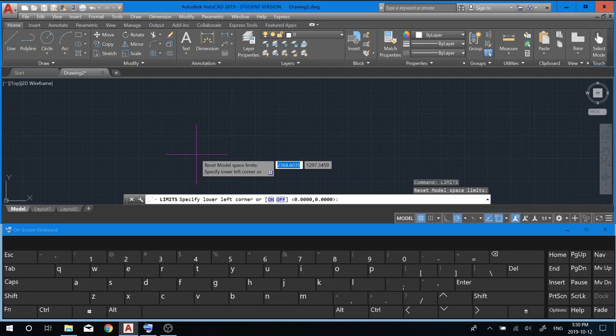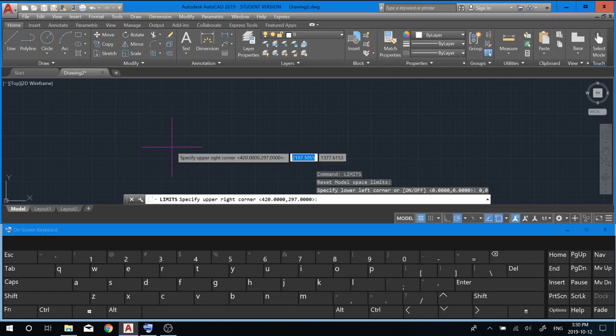So we're going to set it to 0, and then we need to shift over to the second box, which you can't do with your cursor, because if you move your cursor, it just moves the whole thing. But to jump over to this box here, you have to hit either comma or tab. Either comma or tab will swap over to the next box, and 0, and I'm going to hit, once again, spacebar, not enter.